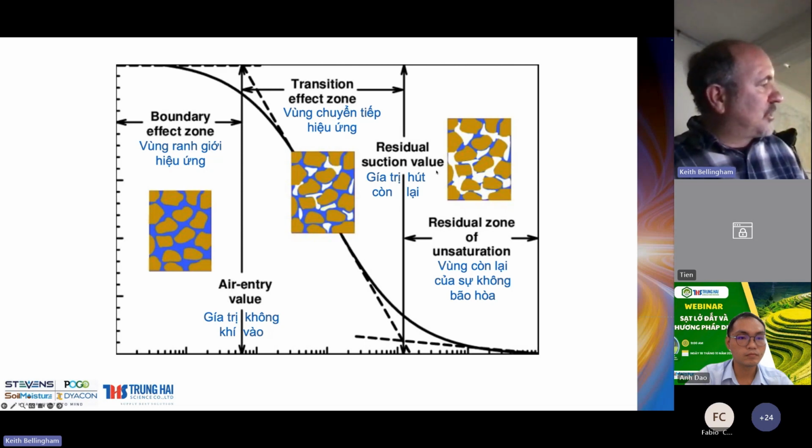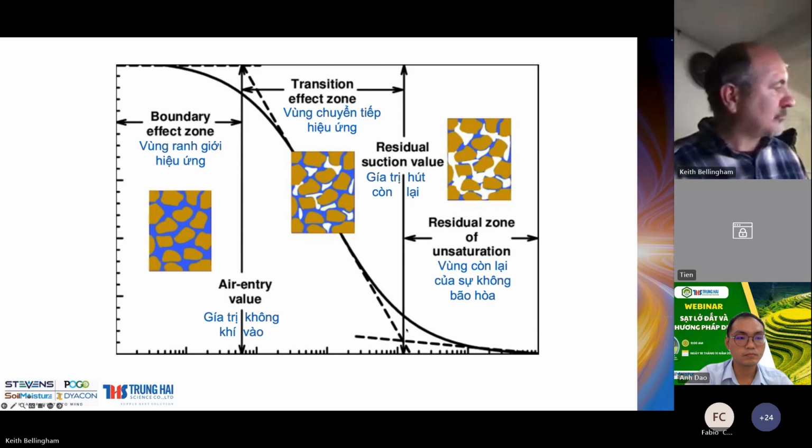And then at soil residual is where the pockets of water in the soil, these little microscopic pores, become broken. They become disconnected from one another. And we see this on the soil water retention curve, because it's when the pressure starts increasing, but the soil moisture stops going down dramatically.